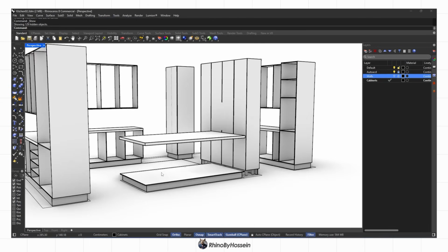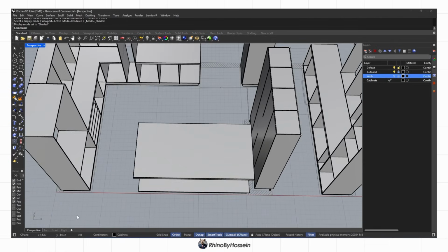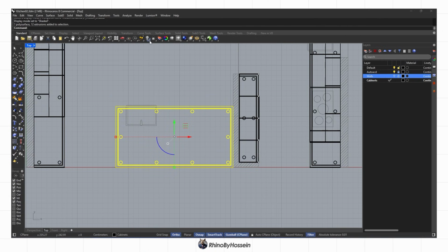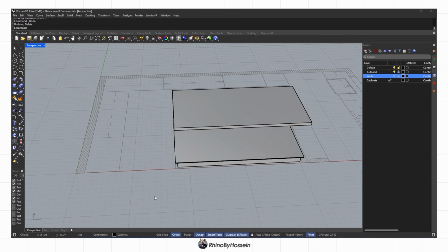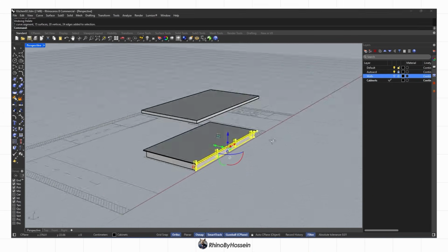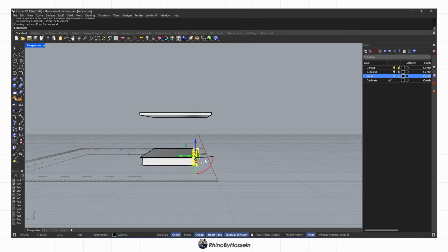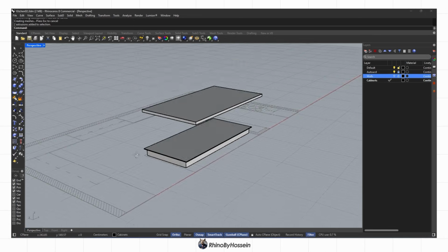Now we move on to modelling the kitchen island and making small adjustments for user comfort. To ensure people can sit comfortably on the bar stools, the island cabinet, except for the countertop, is offset slightly inward. To do this, I hold Ctrl and Shift, select the bottom edge along with all the legs, and push them inward about 20 centimeters using the gumball. The middle legs are also moved 10 centimeters to maintain proportion and symmetry, keeping the island centered.